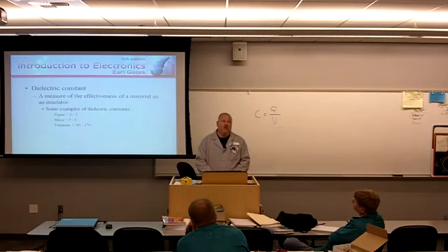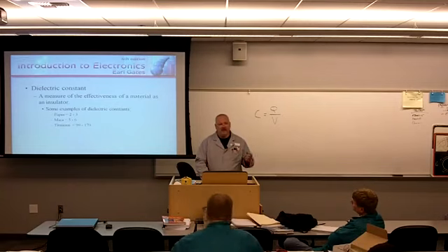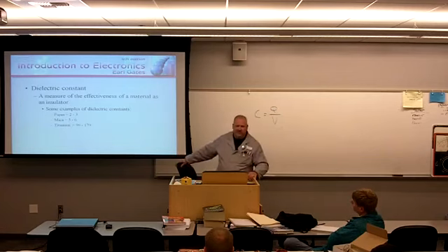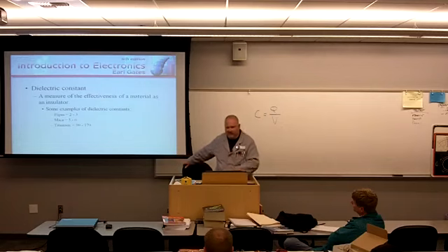Wax paper used to be used as the dielectric, as the insulator, in a lot of capacitors prior to World War II. I've restored many an antique radio by simply going in, removing the paper caps that have deteriorated, and putting in mica caps of the same value. Just that easy, remove it. Everybody always gets an old radio, and oh yeah, it must be them there tubes. Them tubes there need to be replaced.